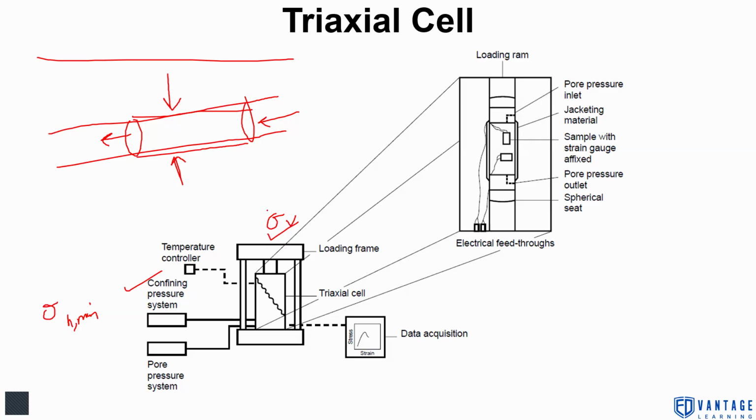In a triaxial test, we confine the body with a radial fluid pressure, of 1 bar, 10 bar, 5 bar, whatever it is, and we give the load on this body on the axial plane. Our objective is to see the shear failure line of this body and up to what load it can handle. So we plot stress versus time, and we will see that if we keep increasing stress, at one point the body will fail and release the stress significantly and instantly.